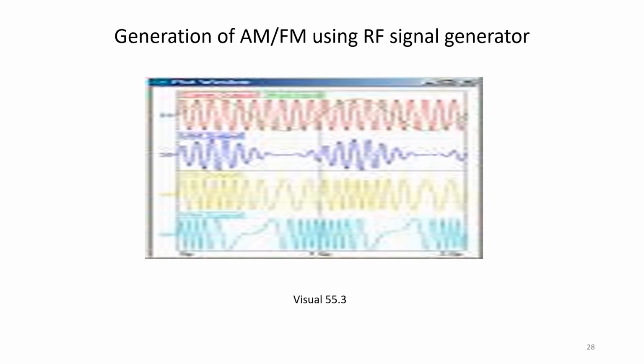So to prevent the RF interference between the components, to prevent the emission of RF energy from any point except the output terminals, and to prevent RF emission on the power line, RF chokes and capacitors are used.